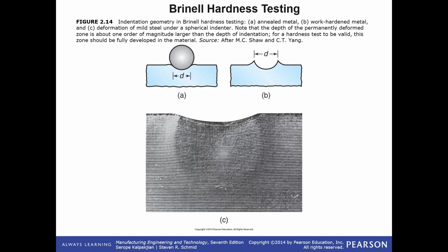The Brinell hardness test. This is something, again, we have in lab, and maybe I'll show a demonstration at least with this. These are a little bit harder to do because you also have to have a magnifying glass or a scope to look down. So essentially, you do the same test and you push a ball into a piece of metal using a high amount of force.